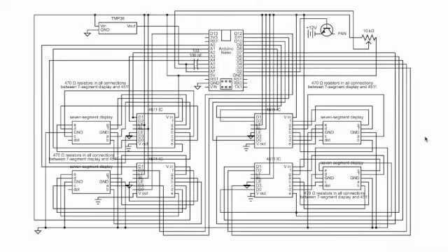This is the circuit diagram of the circuit. From this diagram, we can see how the circuit exactly works. As you can see, inside the circuit, there are 4 different pairs of 7-segment displays, each paired up with a 4511 integrated circuit. The pins A to F on the 7-segment display are connected to corresponding letters A to F on the 4511 integrated circuit. Then, pins D0 to D3 on each 4511 are connected to 4 pins on the Arduino Nano.